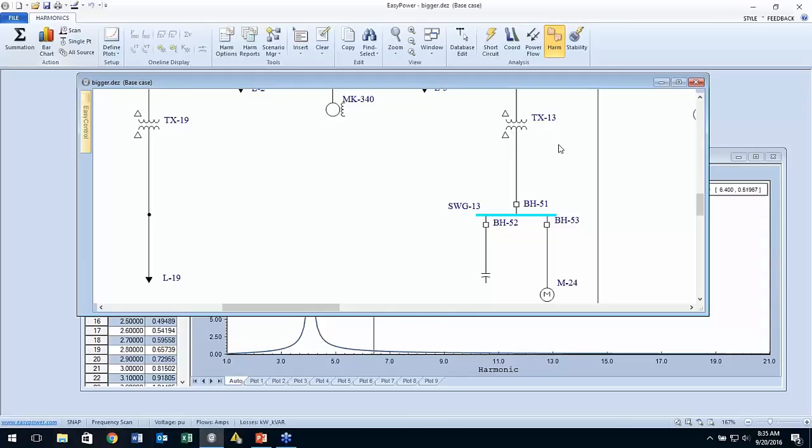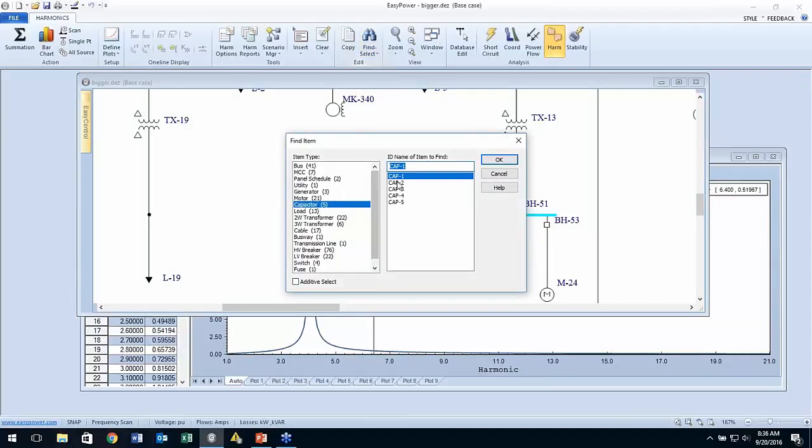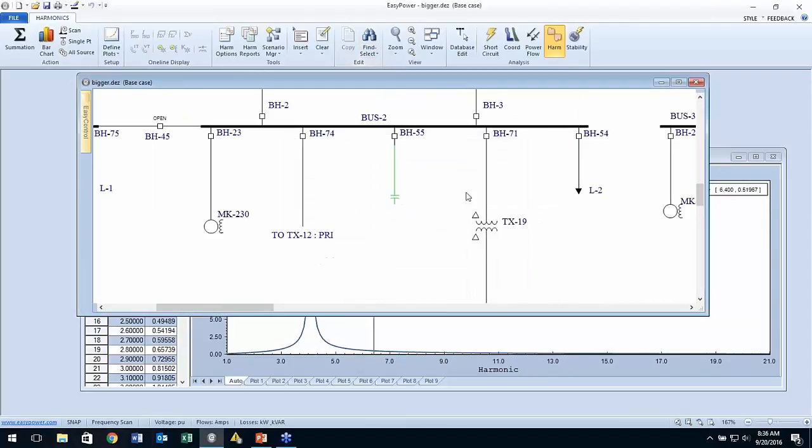And at that point, when you're kind of down the road and you're just seeing a bunch of system issues, you are better off suggesting a harmonic study be done, and by using, at a first pass, just as I'm doing here, looking at, in this case, the high value capacitors, those would be the places we'd start off looking at, taking data log measurements for harmonic content and power quality measurements.